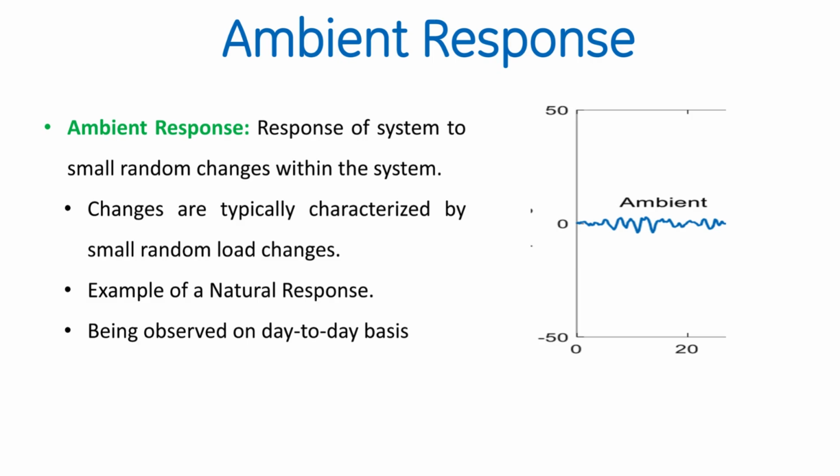That's fascinating. So if it's happening all the time, this sort of low-level chatter, how do grid operators tell the difference between that normal ambient stuff and, say, a real problem that's just starting to emerge? Yeah, that distinction is absolutely key. It often comes down to the magnitude and looking closely at the frequencies involved, spectral analysis. Oh, okay. Ambient responses are statistically small, they look random, and crucially, they're usually heavily positively damped. They die out fast. Right. A real developing problem, even one that becomes sustained, typically shows up as a clearer, larger signal at a specific, often worrying frequency. But that constant background noise, that's why monitoring systems need to be so incredibly sensitive and sophisticated.